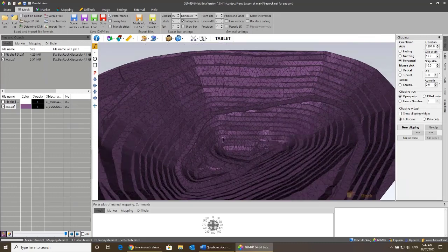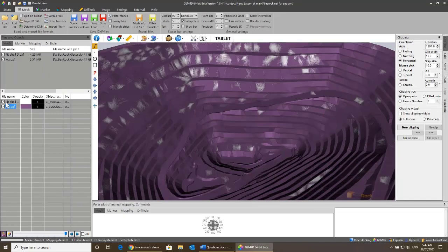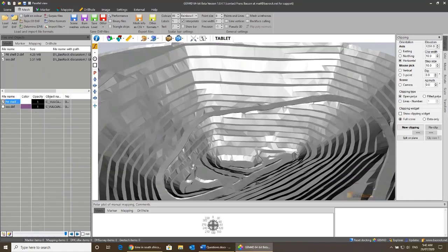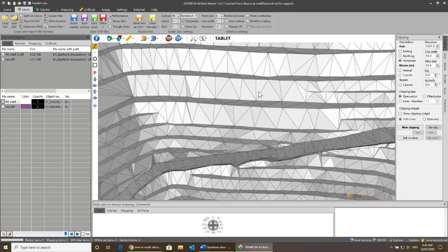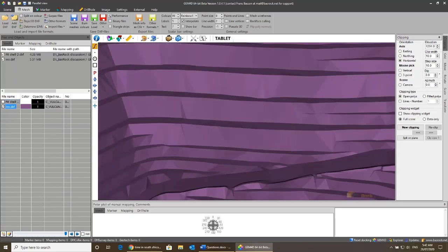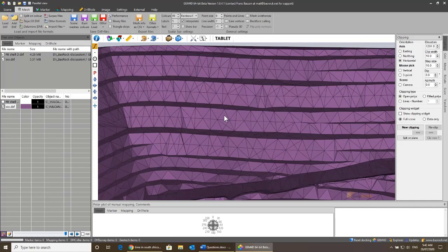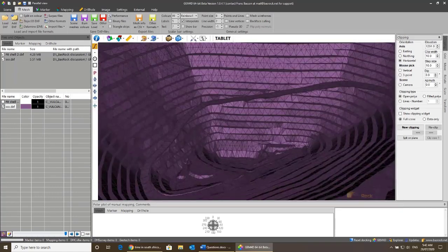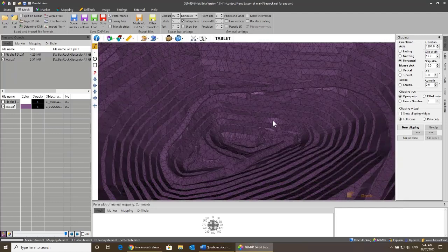So if you compare the first one with the second one, you can see the first is the original data set. Each one of these benches has only one mesh height, and in the new one they're subdivided into two. So you split it into more points. And because you've got more vertices now, you'll get a cleaner outcome from this process.